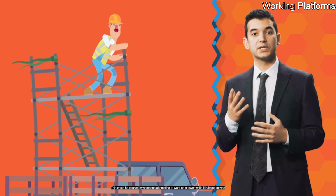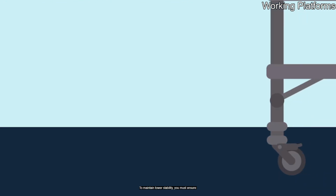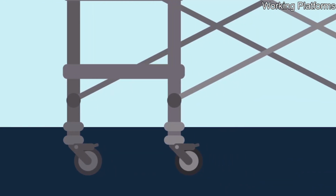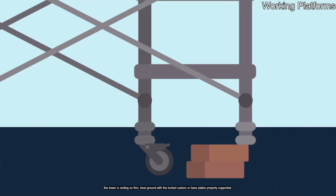This could be caused by someone attempting to work on a tower while it is being moved. To maintain tower stability, you must ensure the tower is resting on firm, level ground, with the locked casters or base plates properly supported.